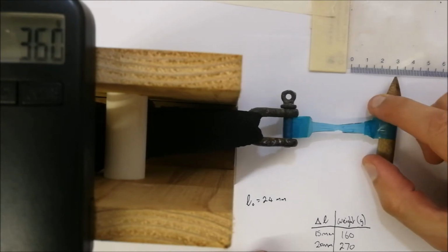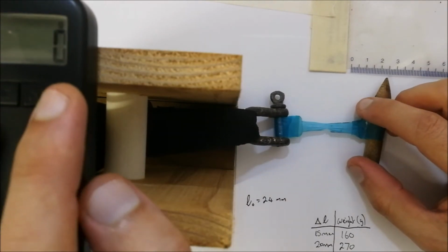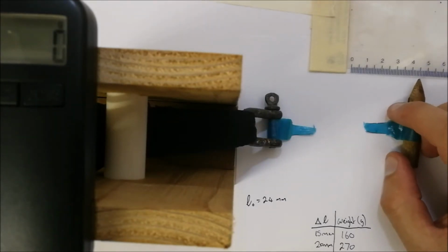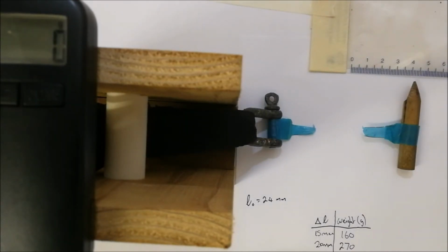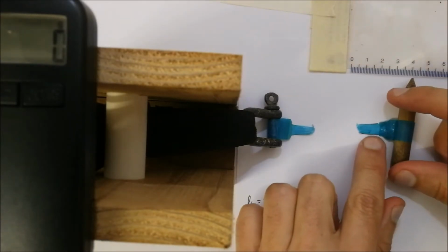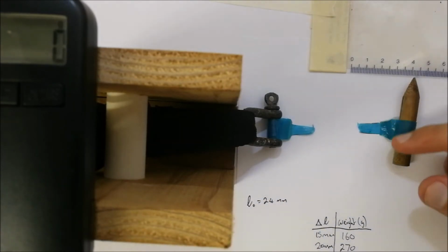Okay, so I'm just checking, you'll see the necking over here decreasing. So let's just go back again. Okay, let's go to 40. Go into 40 and it breaks. Okay, so at 40 millimeters it breaks. And you'll probably find that the reading was very close to that 300, and we're not going to worry about that. Okay, so as you saw, it did thin over there, it did cause a thinner neck, and then it broke over there.